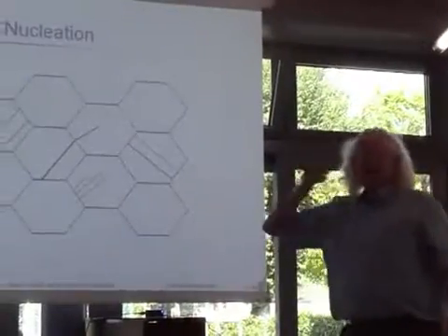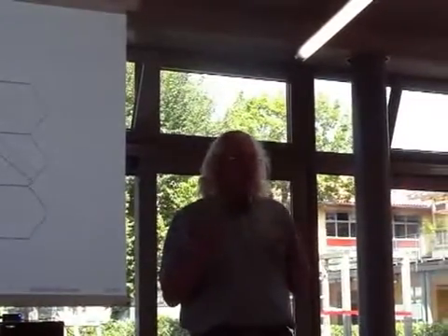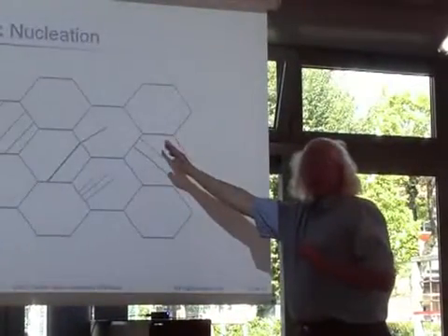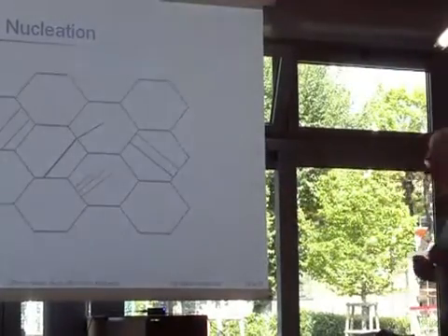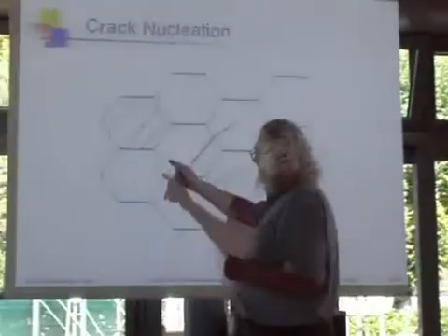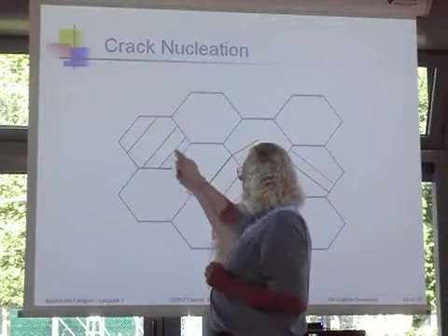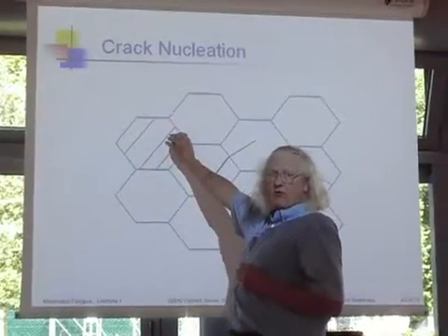So, nothing happens here. And so, first of all, we see that the idea of fatigue has to be a statistical process, doesn't it? What are the chances that the applied loads can activate different planes in a material? And when those line up with one another, then you can form fatigue cracks. Okay. Other things to note. If we look over here we can see a particular grain, and we see these bands that form here, but they are contained inside of this grain. That is, they don't go outside of it.